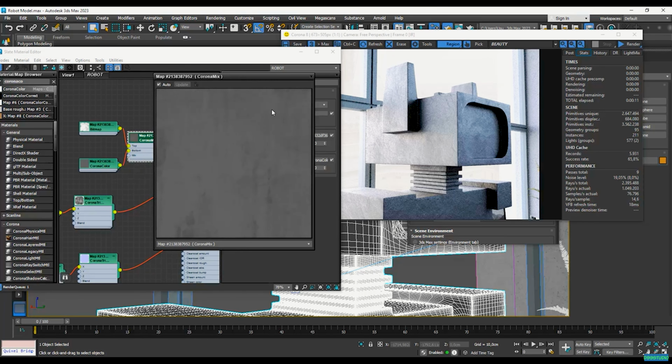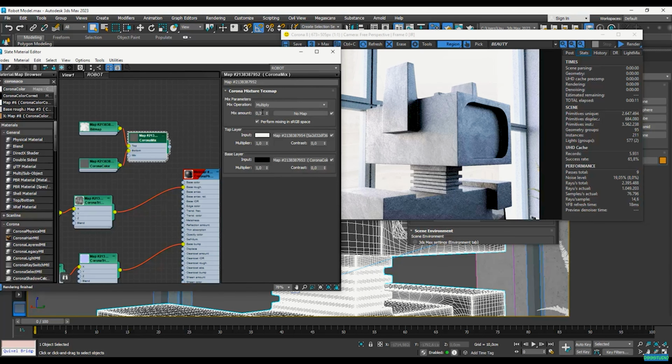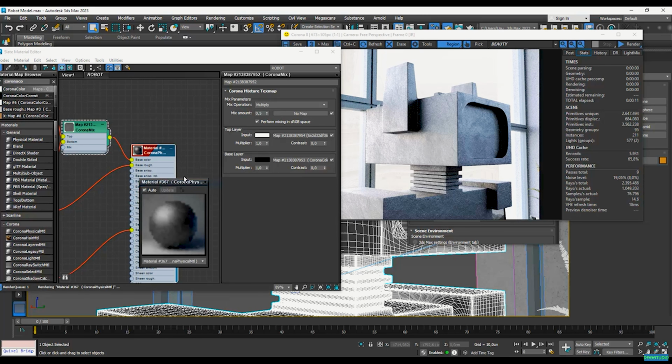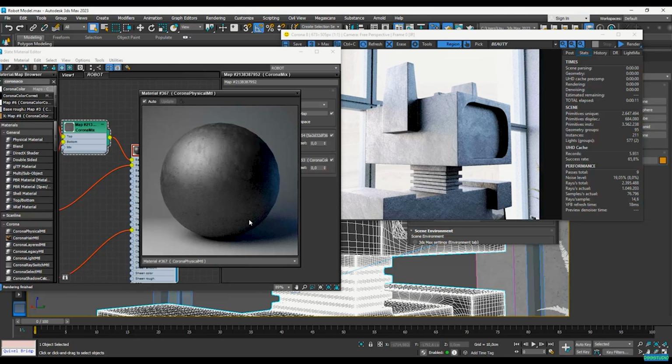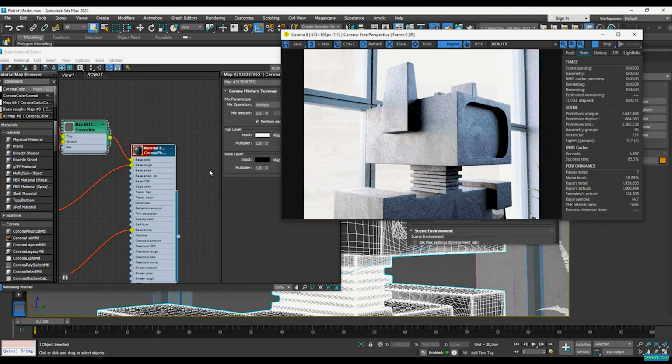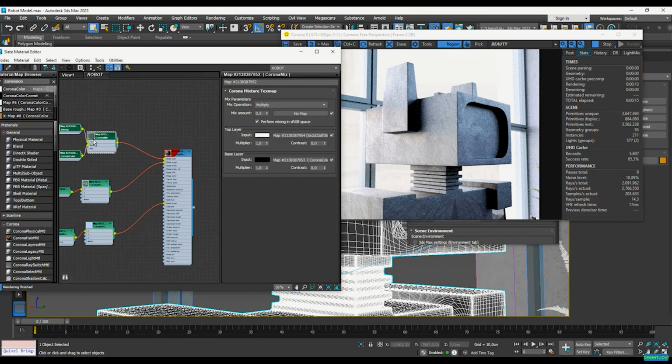Let's check the preview window again. And you can see that this is much softer, but maybe it's too soft. Let's try 0.5. Let's go for 50%. Now this component is going to go inside my base color. So let's just right click and open my preview window. And you can see that we start to see these darker spots appear here. So I'm going to start my interactive render. Actually, we forgot to add a triplanar again. So let's grab a triplanar.